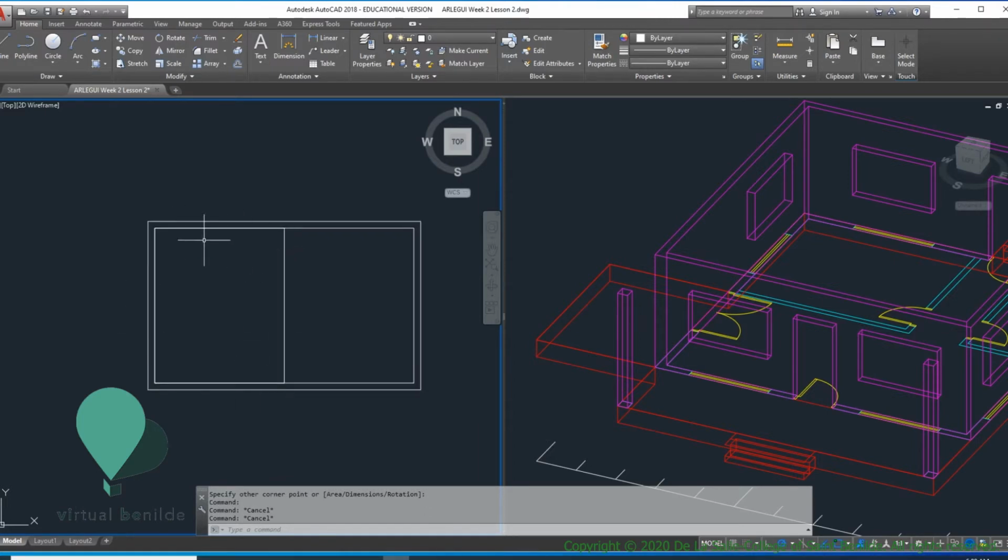And then of course the window panel will have a frame, and within that is going to be where the glass is, and holding the glass would be the inner window frames, which will be the mullions. I'm going to offset this by 3 inches or 0.075. Offset. Value is going to be 0.075. Enter once. Click that. Go inside. Click in there. And enter to get out of the command.